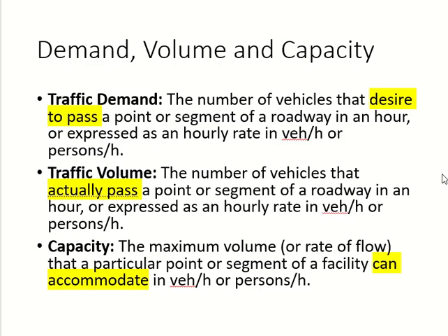Okay, but the volume, will it remain the same throughout the day? I have 2,000 vehicles in this hour. Next hour again 2,000 vehicles? No, right? This changes according to what? According to demand. Okay, the volume changes according to demand. Capacity is something which we fix when we are designing the highway, but volume, actual volume, increases and decreases according to the demand. Demand is how many people want to use the highway. Normally, all three of them are measured per hour for traffic flow analysis.